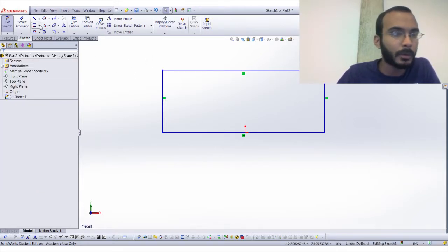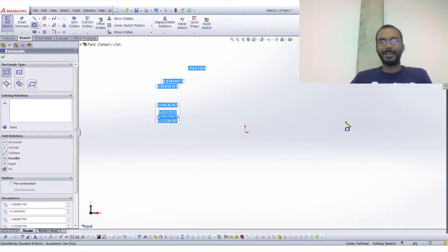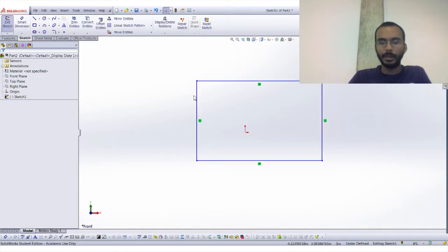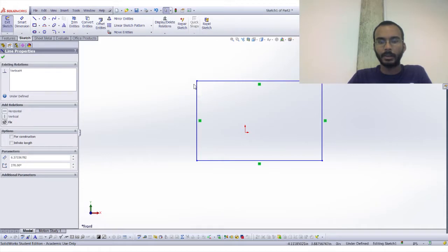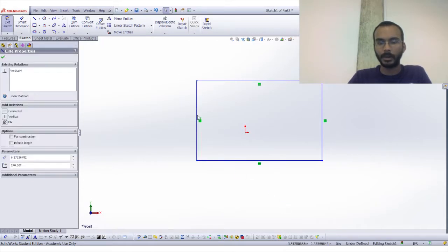So if you select, oh, actually, something we can start with, because in terms of not knowing how to do SolidWorks, I didn't realize this was important for a very long time, but this is actually really, really useful. So listen up. Depending on which way you click and drag, it selects parts differently. If I start here in the upper left and I drag across, it'll only select things that are entirely contained in my rectangle. So when I select here, it only selects this far side.